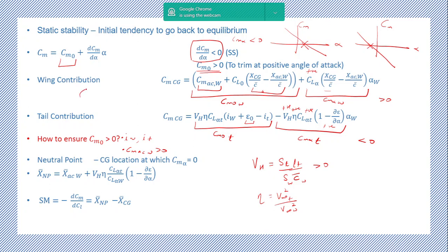Okay, so this is your cambered airfoil, right? So this is your AC. And for a cambered airfoil, your center of pressure is behind, right? So when you transfer the aerodynamic forces, lift and drag, it comes with a pitch down moment.